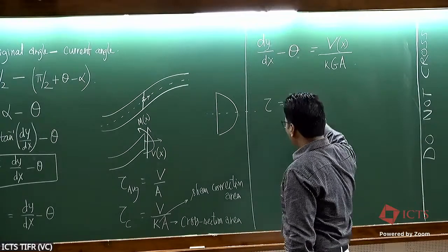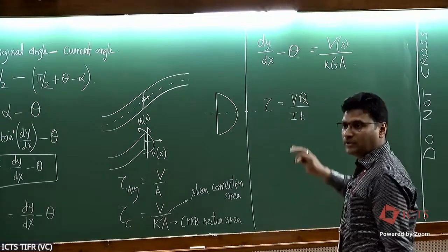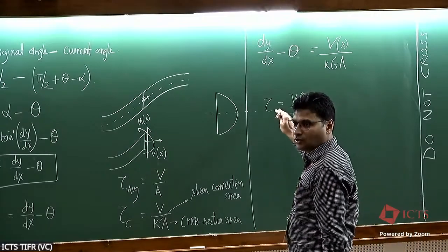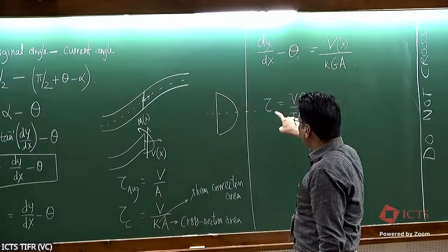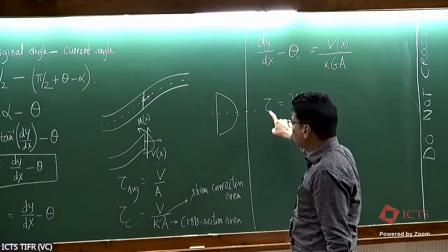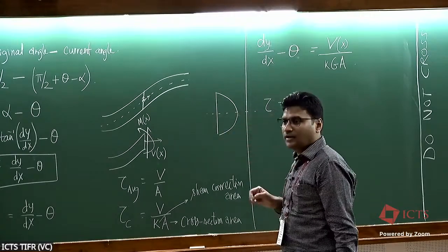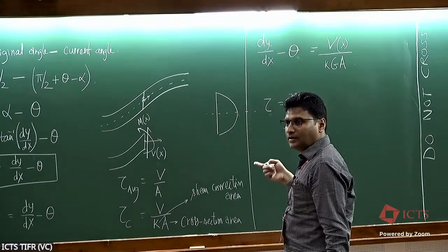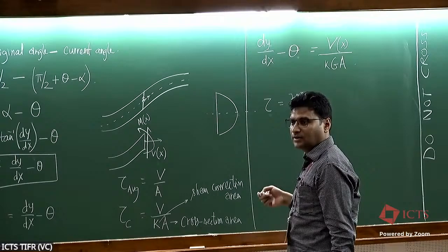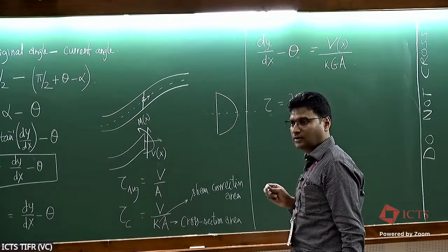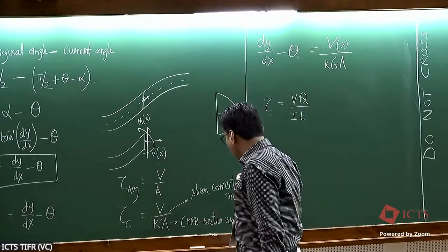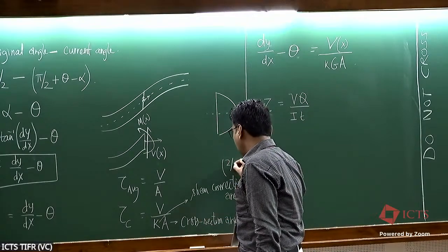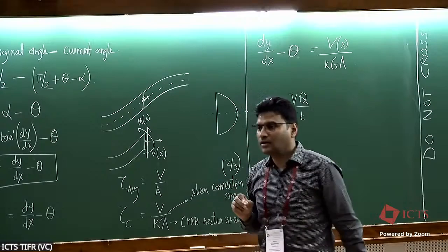There are more symbols coming up. But this is an approximate strength of materials solution for the variation of shear stress. Once you know this shear stress variation, you just find it out at the center and divide that by the average shear stress. That will give you correction factor K. For rectangular cross-section, this correction factor is usually 2 by 3.